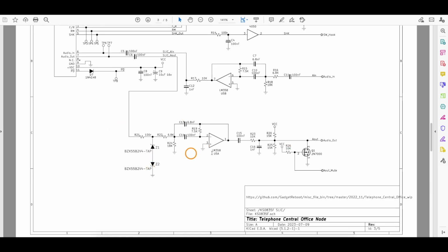So this circuit here evolved to help restrict that from causing too much of a disturbance, keeping it within the regular audio range, and filtering the audio to the normal phone pass band, biasing it up to make sure it stays between 0 and 3.3 volts so it can go into the ESP's ADC, staying within allowable positive voltage range.